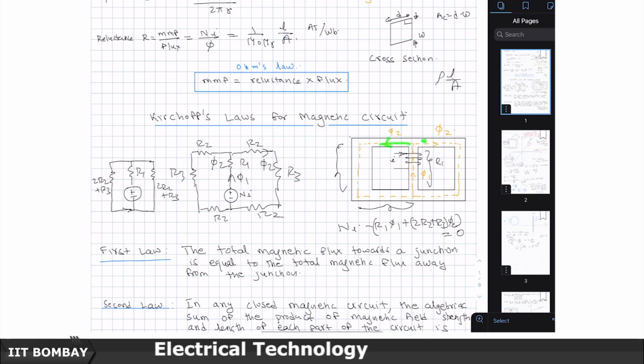So, they will either break here or they have to flow like this, and therefore, if I think of this as a junction, I can say that the flux entering this junction is equal to the flux leaving this junction, which is essentially the statement of Kirchhoff's current law, which did not allow charge to be accumulated at a junction and the charge had to flow. So, if the charge is coming to a junction, which is the current coming to the junction, then the charge has to dissipate out without accumulating at the junction.